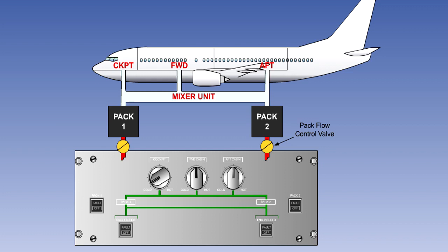The temperature of the air delivered by the packs is determined by the zone requiring the coolest air input. This will normally, but not always, be the flight deck.